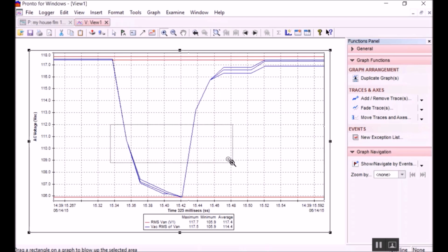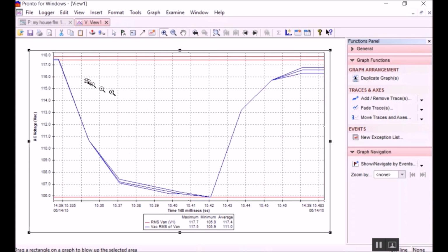And you can see with the interval or point store, even though it showed us a 1 minute sag, the sag was in essence only 148 milliseconds. Ahora con esta opción podemos ver que en realidad en vez de un minuto la caída de voltaje duró 148 milisegundos. And that's the power of the adaptive store. Y esto es lo lindo y lo bonito de tener la opción de la memoria adaptiva.